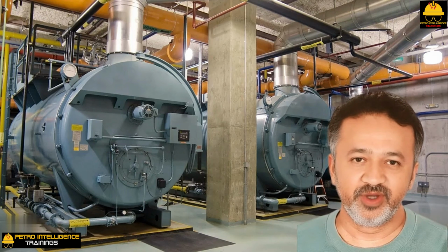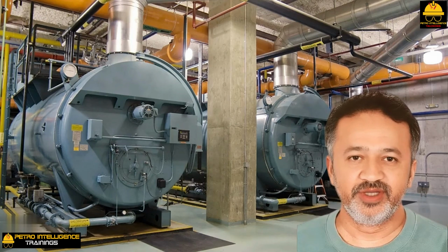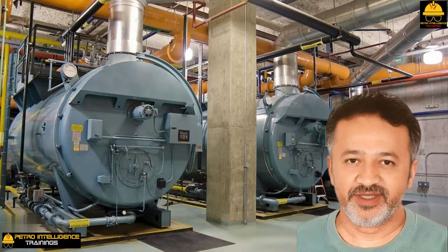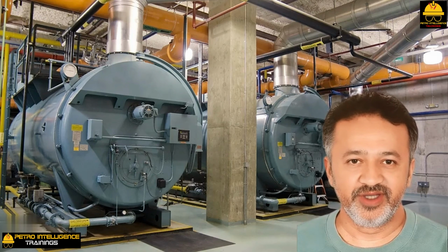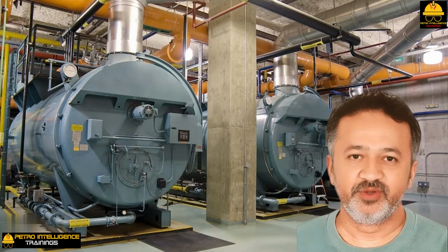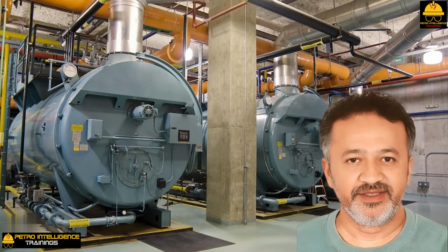The effluent from the deaerator, 230 degrees Fahrenheit, will then typically flow to the boiler's convective section, economizer zone. This usually consists of 4 to 6 rows of tubes at the top of the convective section, where the BFW is heated to 350 degrees Fahrenheit to 450 degrees Fahrenheit.